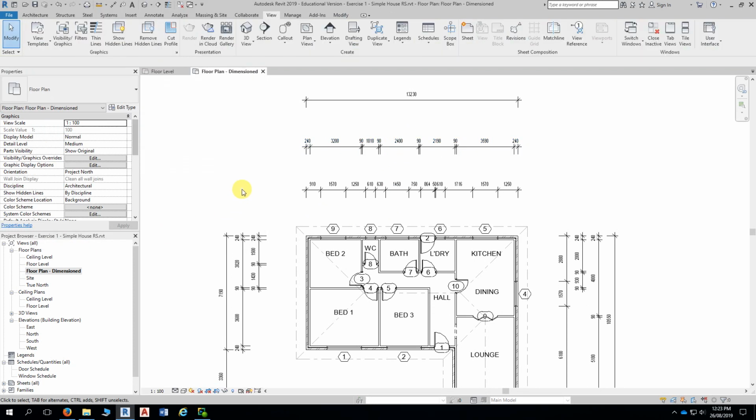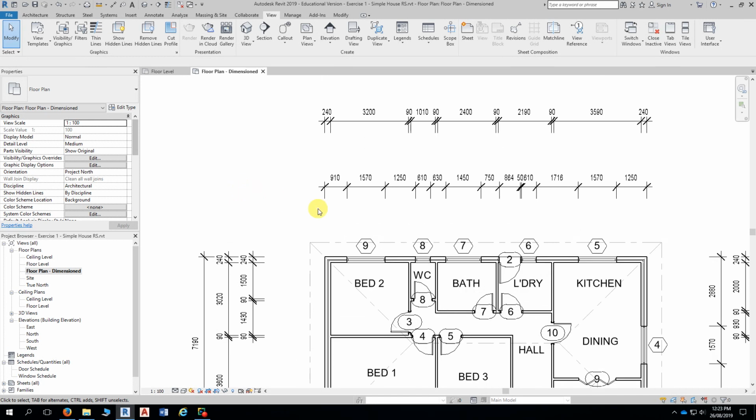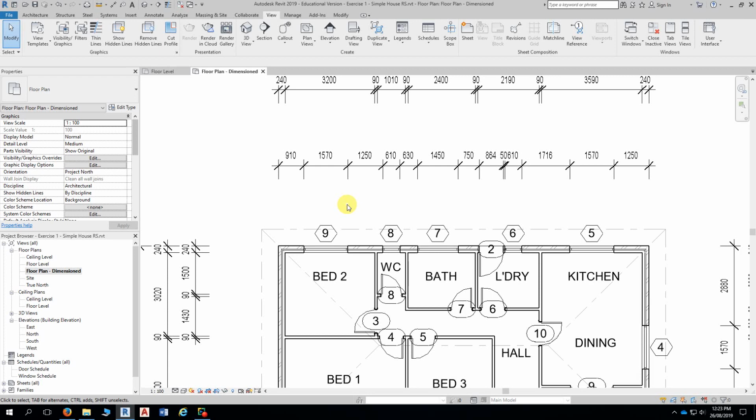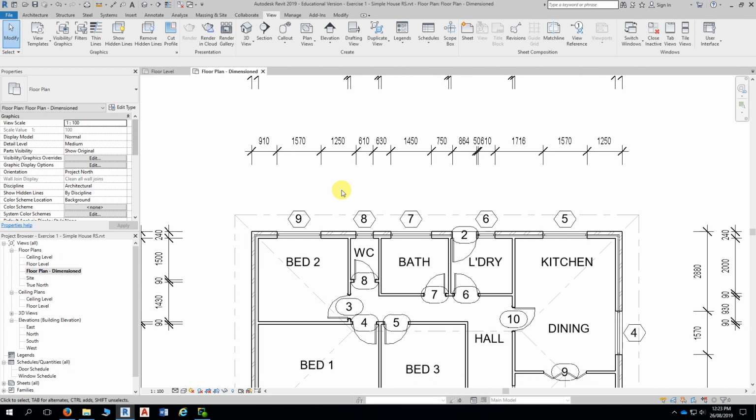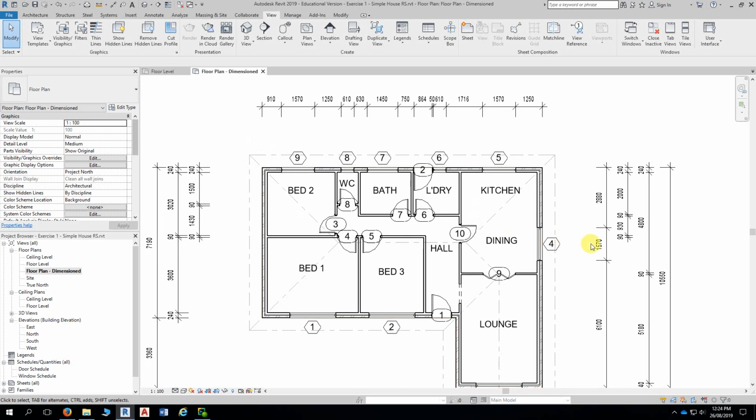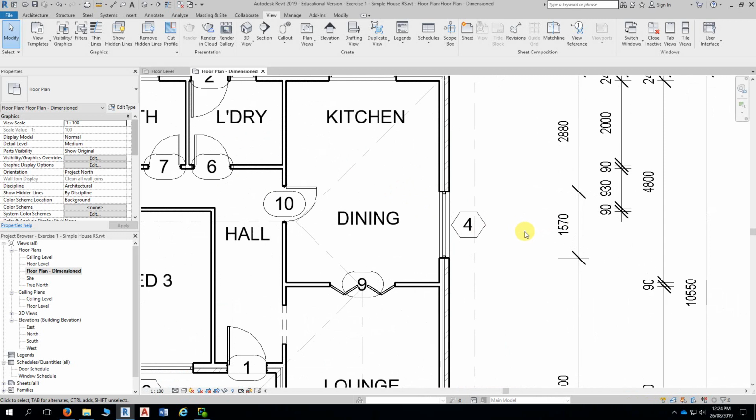See how it's actually squashed them? It's made them narrower. So what that does is just makes them more readable. So it squashes them so they're not banging into one another, you know, where the dimensions get quite close. I'm struggling to read it at all with that 0.7. Can you zoom in? Yeah, so they're still 2.5mm high, but they're actually at 0.7. So you can change that back to 0.8 if you want to, or 0.85. But I thought that was a quick change, just so that they would be readable.